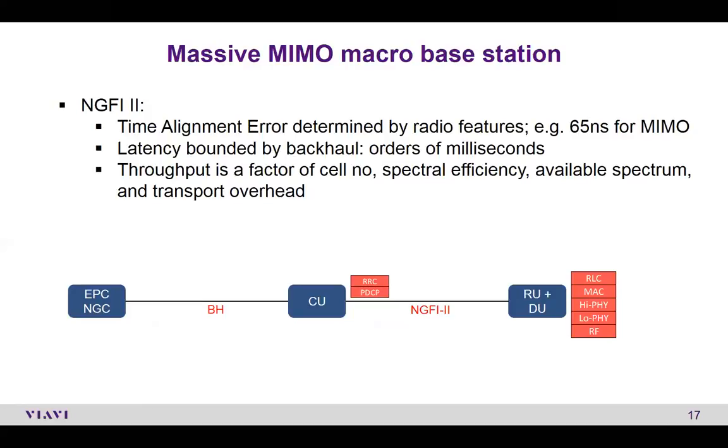Yes, good question. So this is when we go back to this timing measurement. Let's start with this one, 65 nanosecond, right? So you have a radio here that is in the neighborhood, and then you have a central unit somewhere farther away. Typically operators use dark fiber, so the only test access point would obviously be here towards the central unit. Here you are on a pole, not a nice place to do measurements. Then you would do it at the central unit.